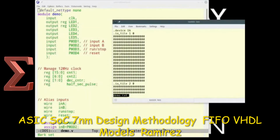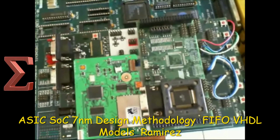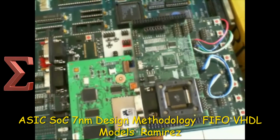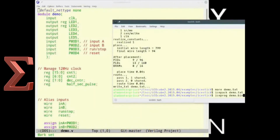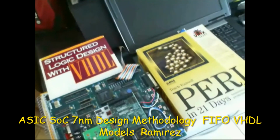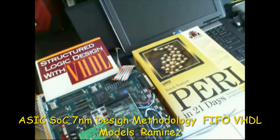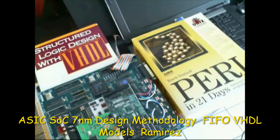However, executing the elaborate command performs the following tasks. It translates the design into a technology-independent design, that is GTECH, from the intermediate files produced during the analysis. It also allows changing of the parameter values defined in the source code.